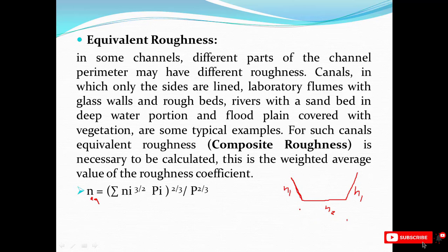At the side, if it's trapezoidal, we should find p equal to b plus 2y root of 1 plus m squared.